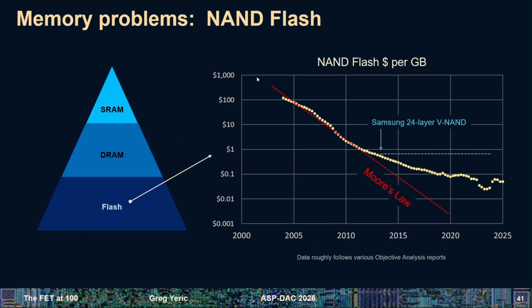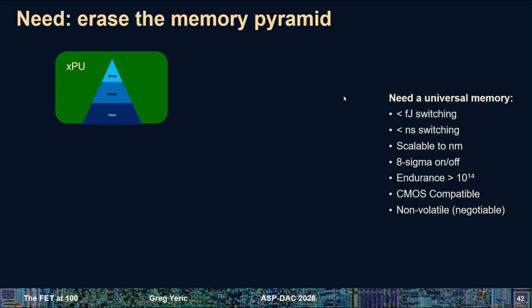So we have what we as users of these transistors need, which is super fast, super low energy, energy then speed, and small, so you get as many as possible on a wafer. You need 8 sigmas. So in terms of a Gaussian distribution, one of the big buzzwords forever in the industry was 6 sigma, and that was what companies like Motorola used to do process control, modern process control. Japan really pushed this a lot in the 80s. But when you count out the number of bits you have on a chip, you need to go to an even higher degree of control.